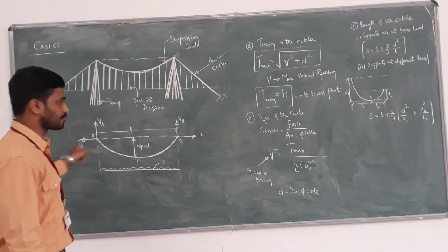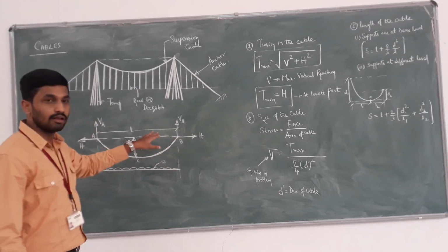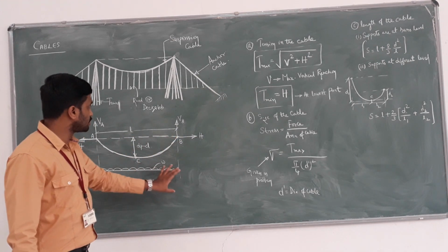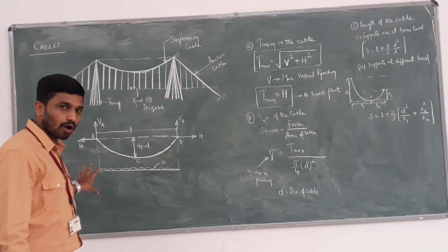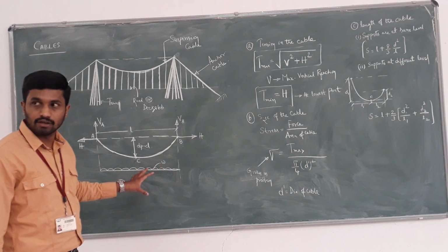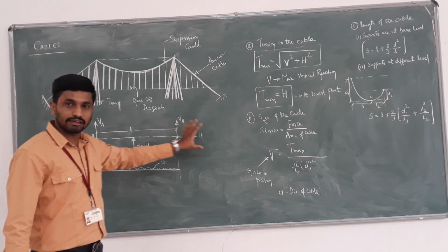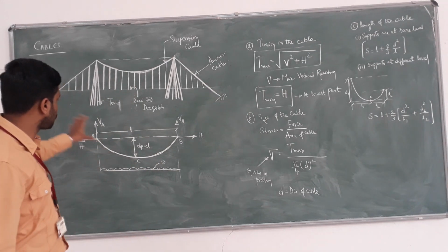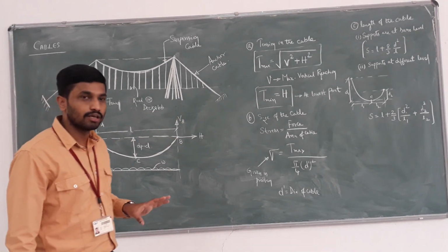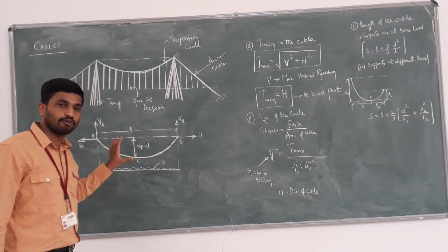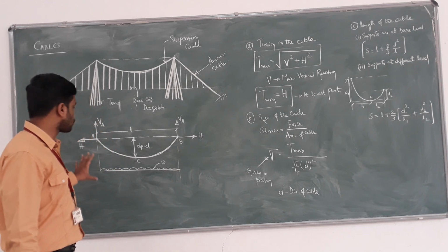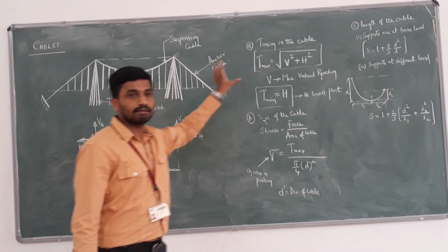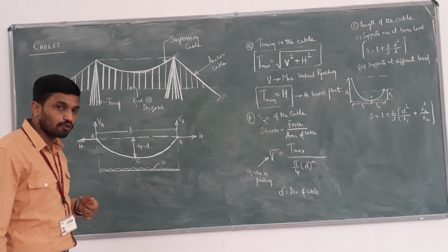Here also it is a symmetric cable, symmetric in level. Therefore A and B are both at the same level. It carries a uniformly distributed load, for example from a slab load. VA and VB are the reactions. In this analysis also, the first step is determination of the external support reactions, that is VA, VB and H. These are structures holding tensile forces.